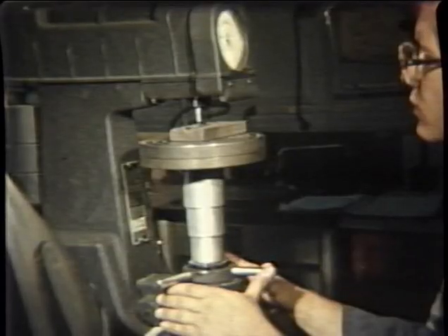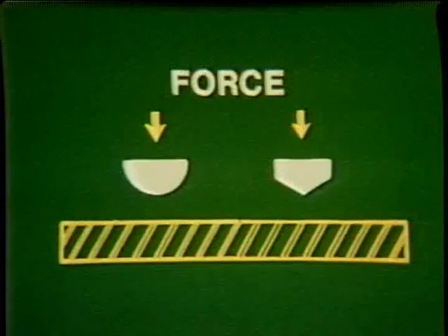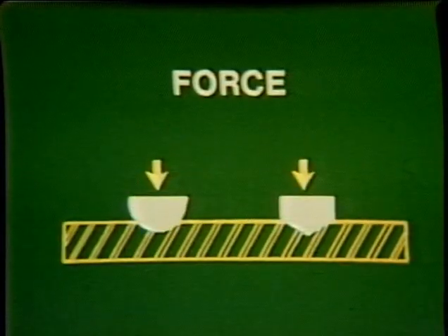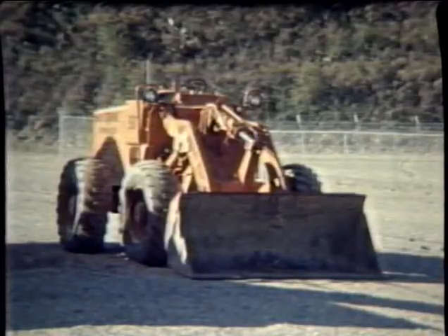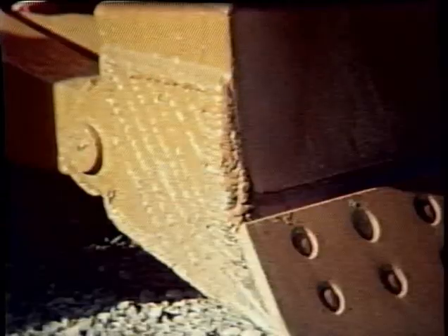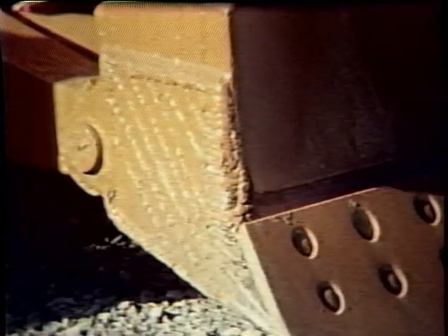The property of hardness is the metal's resistance to indentation from the force of a hardened substance. Hardness is measured by forcing a hardened steel ball or a diamond into the surface of a metal. The Brinell, Rockwell, and Vickers tests are commonly used to evaluate this property. Although not a common test for weldments, it is sometimes used with weldments which are subject to wear. For example, a bulldozer blade requires resistance to the materials which strike against its surface.